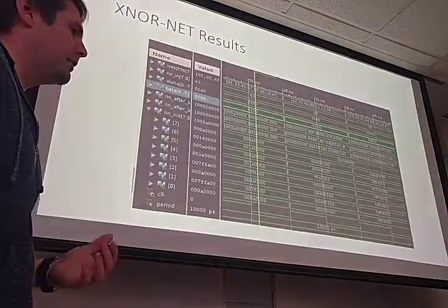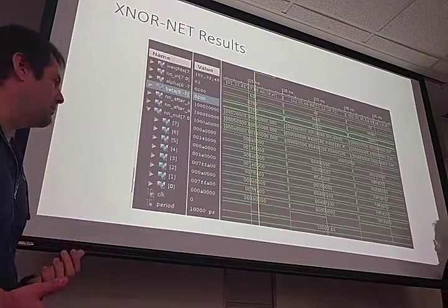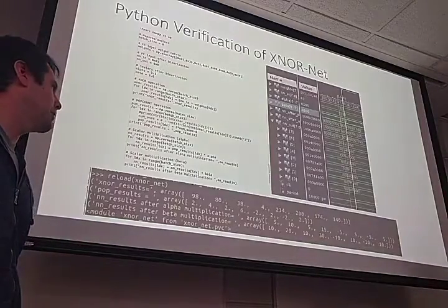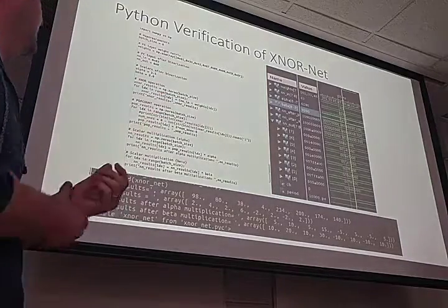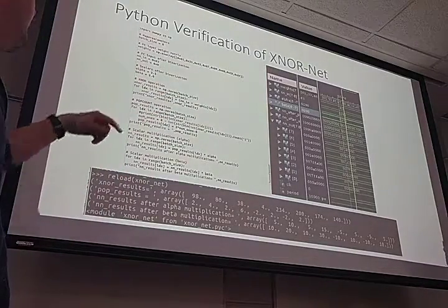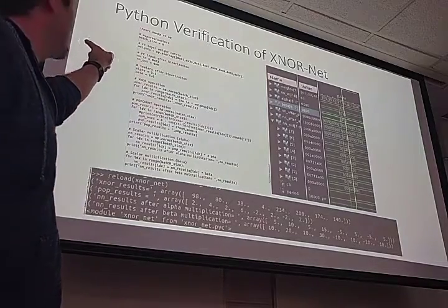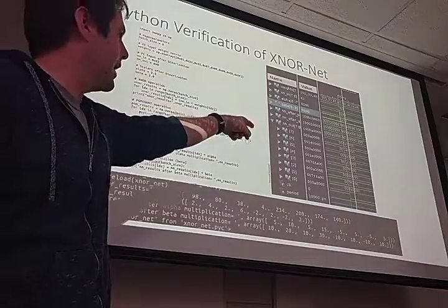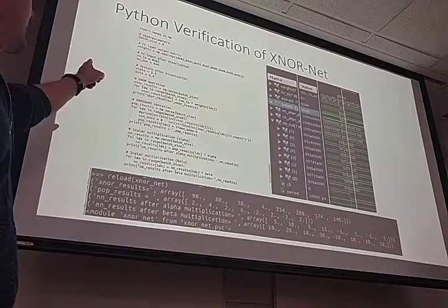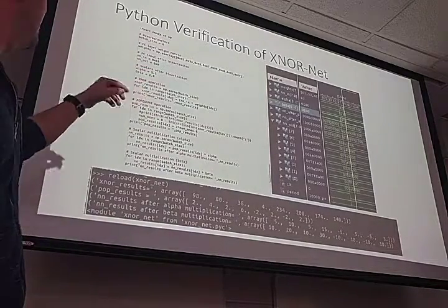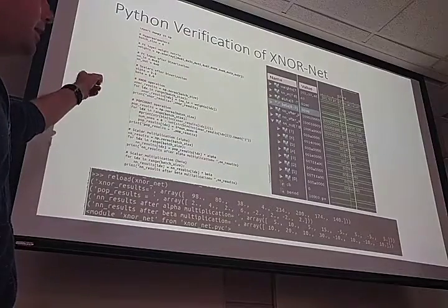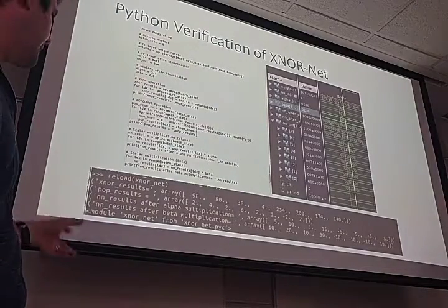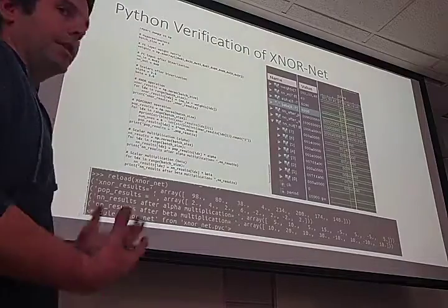On the next slide, we'll show how we coded up a basic Python script to compare the actual results with our hardware-implemented results. This is our Python script here in the top left, and it's using the same weights that we have for this clock cycle in hardware. We have the same neural network inputs, and neural network outputs zeroed initially. We have an alpha and a beta for the scalar multiplier at the last steps. And we do basically the same thing that we did in hardware.